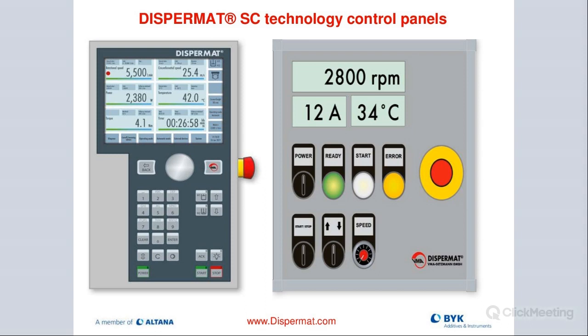So we also have the QC control. We can set that up on the machine itself on the C technology. That's just two examples of what these control boards look like. With the C control package on top here, you can see your speed, RPM. Below that, we have the amount of energy we are putting in the mill base in watts. Your torque value, which is the viscosity measurement. The actual tip speed, which is that critical value we talked about. Temperature and a timer function. And a little bit more simple on the standard M technology, just RPM, amps, and also the temperature readout.